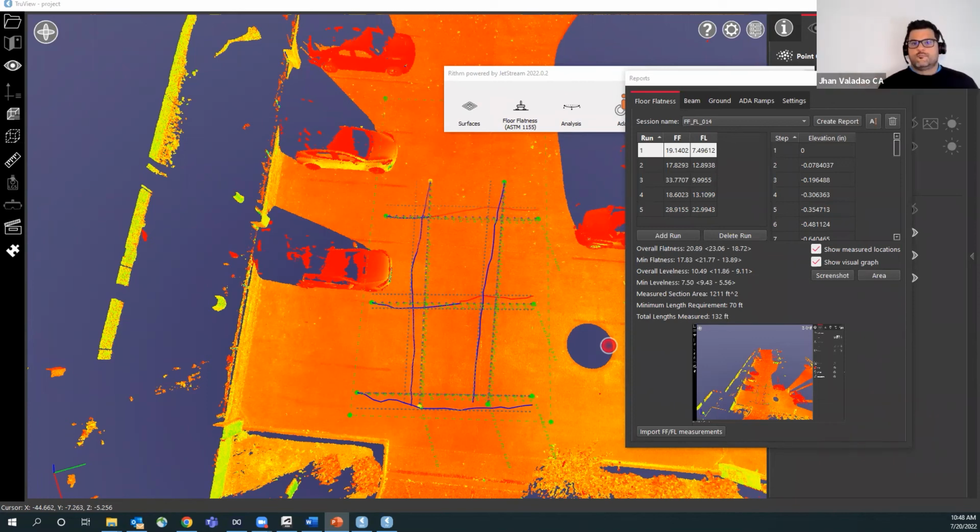So, I mean, the whole ethos of the point cloud and reality capture is data today is now expected to be extremely accurate. In the past, sending a team out to extract information, you just expected floors, walls, and ceilings, and maybe 1 or 2 areas of interest. But now, having point clouds, we can say we need to get things like the duct diameters or the lengths. What are the runs of conduits? What's the grade of the slope? Because you can get this information, a human couldn't. But now we're always getting this information. And the reason why this is all beneficial is because we're not guessing nearly as much as we used to.